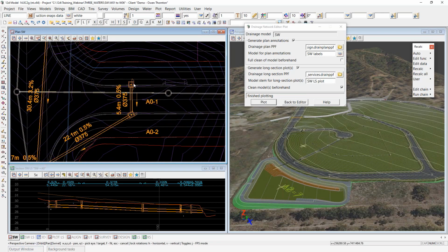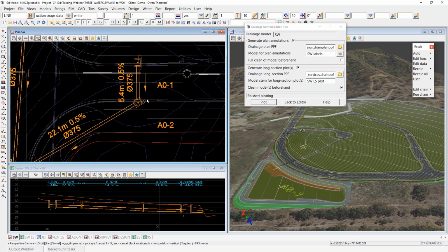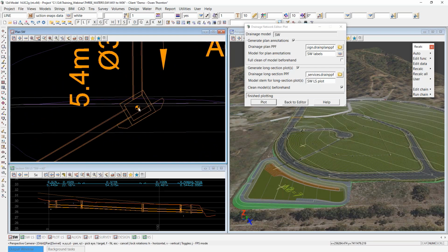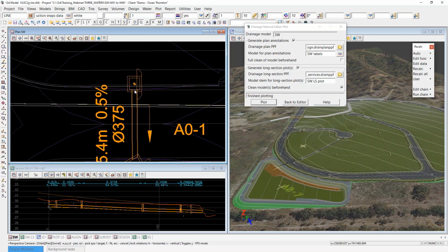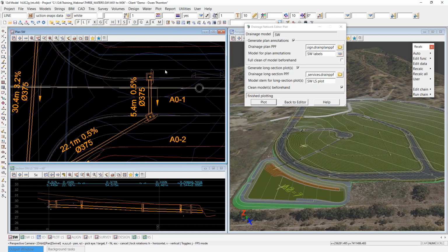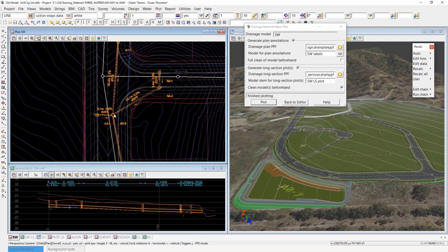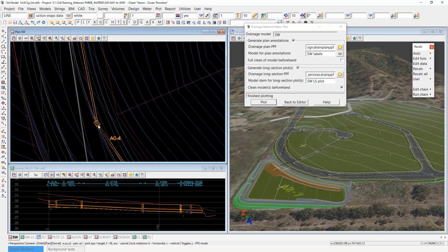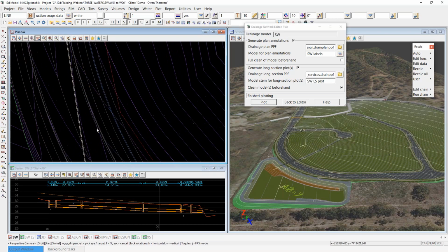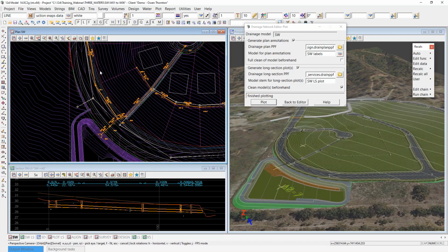I can see my nodes are simply aligning with the downstream pipe, and they don't have the correct node rotations. Also, the setout point, which is this funny little symbol here, is simply in the center of the node where I place the node. It's not where it needs to be, typically on one of the curb strings. Normally, the lip of curb string is used most often in these parts. And so if you had to sort that out manually, it'd be a lot of manual work to go and rotate all of these nodes manually. Entirely possible to do, but why would you?